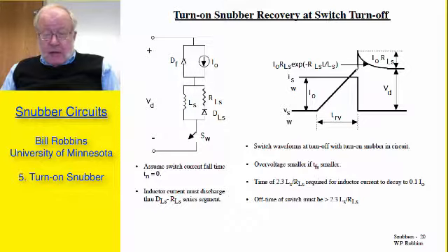When it reaches the power supply voltage, the current in the switch can drop precipitously down to zero, as the freewheeling diode can now conduct, and the energy stored in the inductor, and thus the voltage being generated, can decay exponentially down to zero across the inductor.